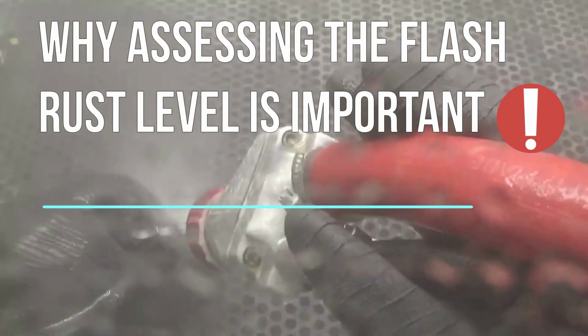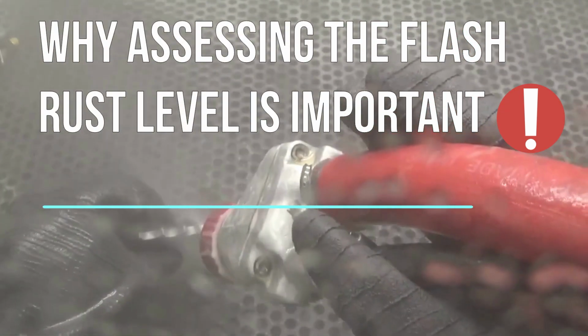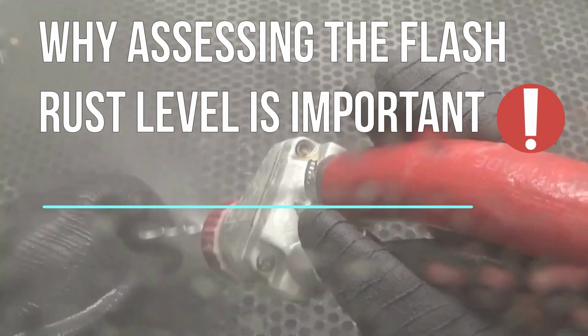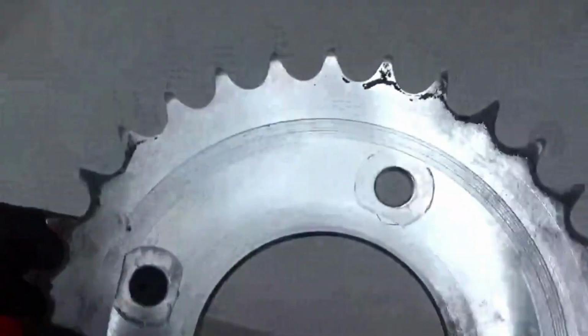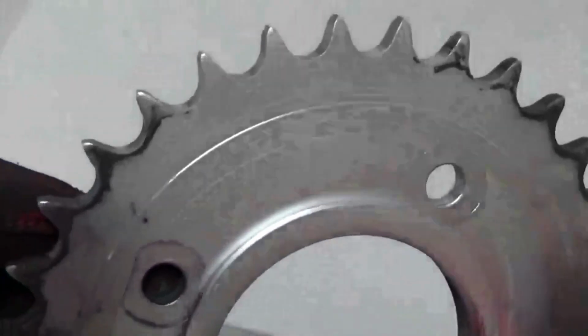Why is assessing the flash rust level important? The cleanliness levels of wet abrasive blasting are identical to those of dry abrasive blasting. However, there is one important difference: the formation of flash rust as a result of wet abrasive blasting. Flash rust forms when the water used for cleaning evaporates and forms an oxidation layer on the clean surface.